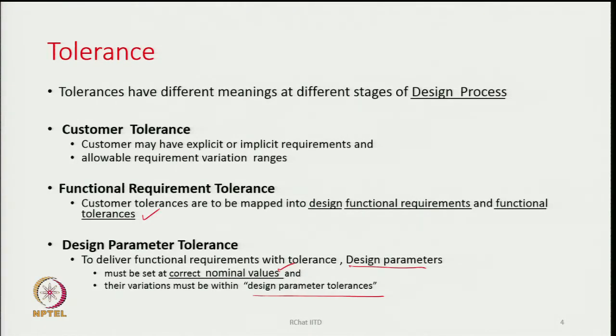Like say strength of a fabric we know depends upon the ends and picks per inch. So, what should be the exact tolerances in ends and picks per inch? That ends and picks per inch become my design parameter. With that I can vary the strength requirement of the fabric in both warp and weft directions, and therefore, they become my design parameters. The count of the yarn becomes my design parameter. So, we need to know what is the nominal value of this design parameter, that means the target value that we should try to achieve, and how much tolerance we should have there.